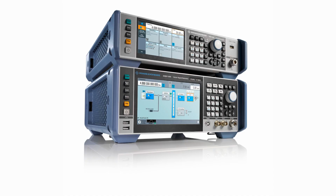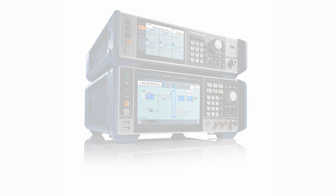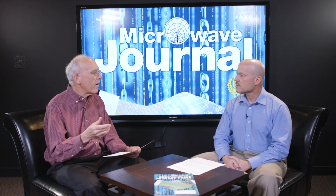So we have 3 product features. The first one from Rohde & Schwarz, some new signal generators. They have a couple variants. One is an analog, one is vector. Basically, otherwise have a lot of the same performance. They have the option of going from 8 kilohertz, either 1, 3, or 6 gigahertz, and then also, interestingly enough, different power levels. So they have the option to go to a higher power level. So in many cases, if you're testing a power amplifier, you'd need a driver amplifier. Now, with the high power option, you don't necessarily need that. So that's from Rohde & Schwarz.